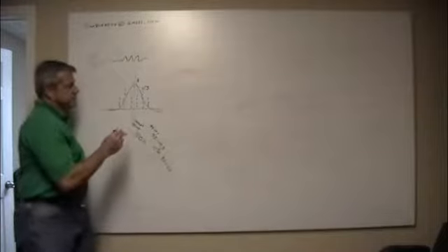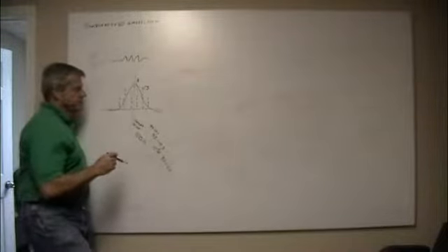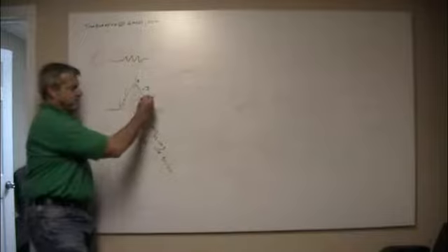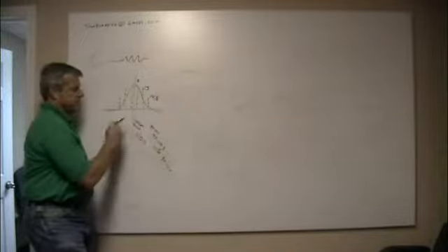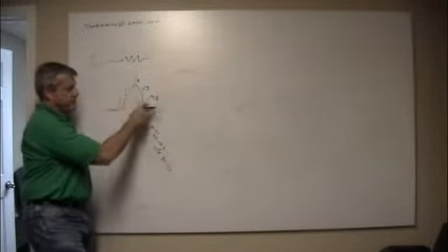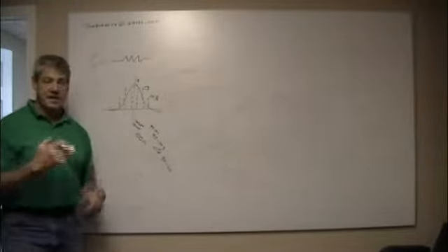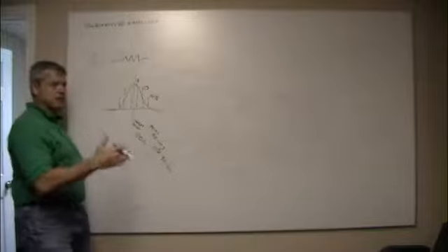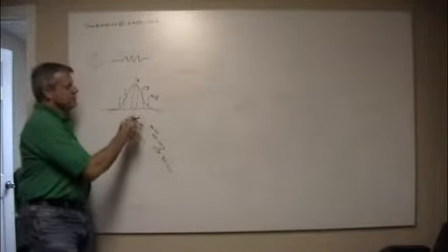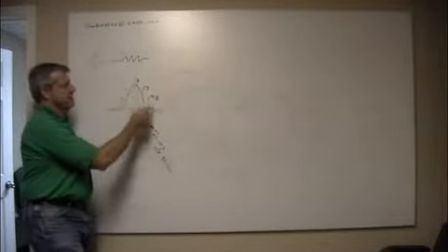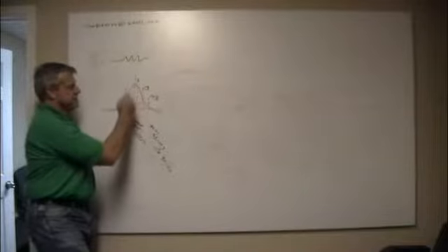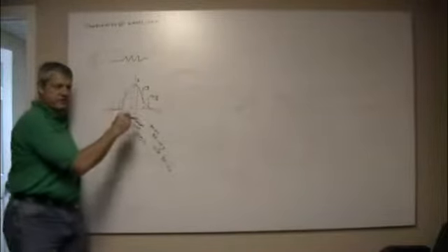Back in those days, people would try to be cheap and go, oh, we'll buy 10% parts. If you do 10%, you've got to do more math to make sure things are going to work in an active circuit as opposed to an analog circuit as opposed to a digital. But people would think, if I look at the distribution, most of my parts are going to be good.